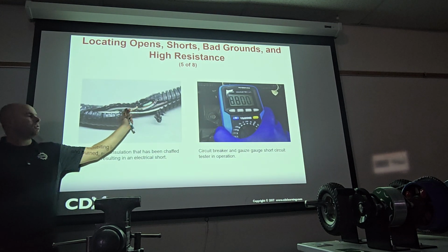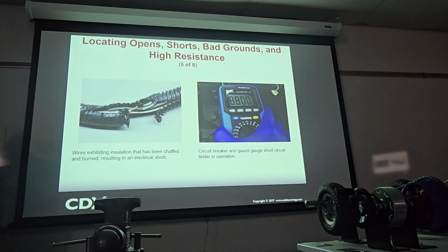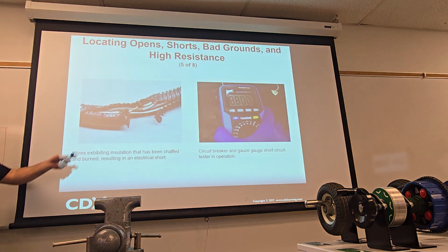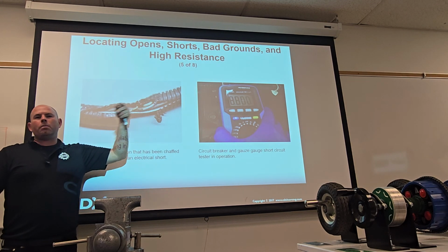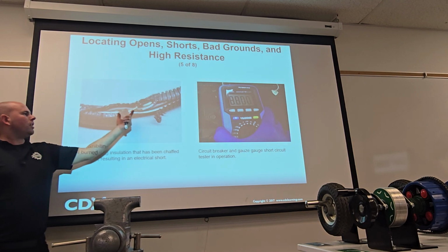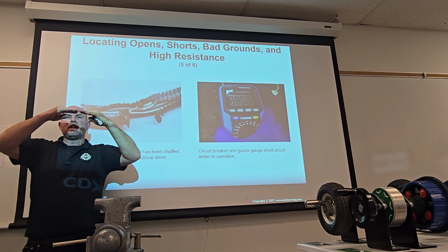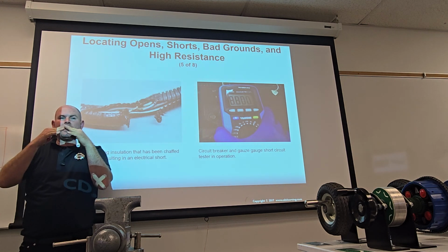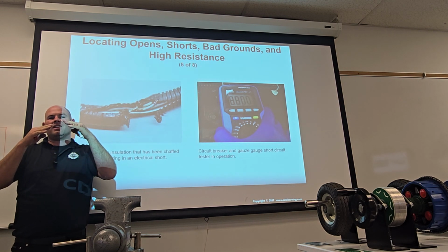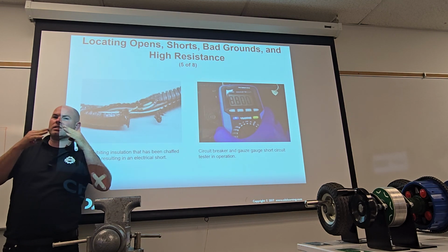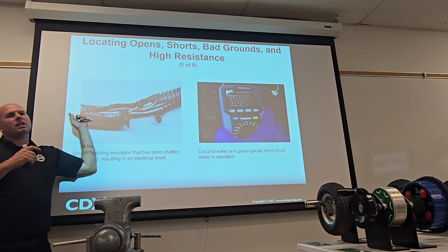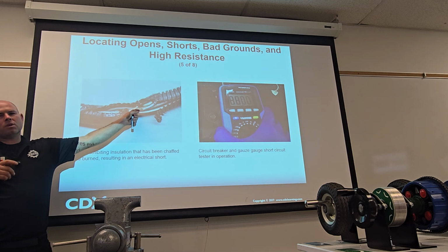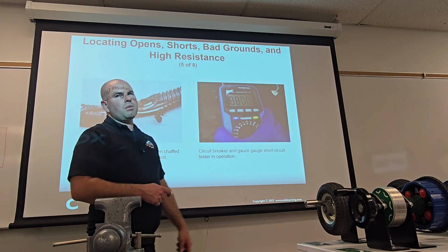Yeah. So depending on the exact details, that could cause a number of those things. One, yes, if it's touching the frame, that could be a short. Another, if it's totally open, that's a complete open. Another, if it's touching and then not touching, that's causing an intermittent. What does intermittent mean? It works, it doesn't work, it works, it doesn't work. What if there's one strand and it's reliably connected, but the other strands are broken off? That might be a high resistance. That could be a dim, right?